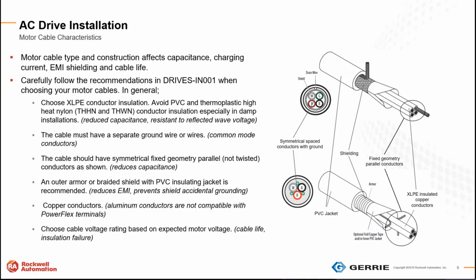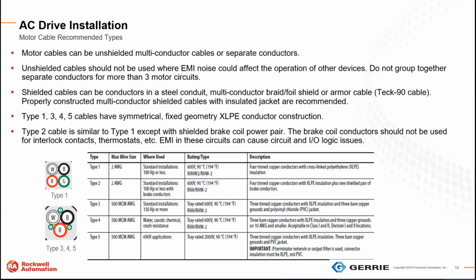It's a great recommendation. That's probably the ultimate installation. In reality, we probably run into more unshielded multi-conductor cables or separate conductors that we typically see in the field, and we do have some recommendations around that as well. What we typically see is sometimes Tech cable being used in steel conduit, and they're assuming that's the grounding portion of it, but we like to see a separate ground conductor in that conduit, so we can get that grounding taken care of as best we can.